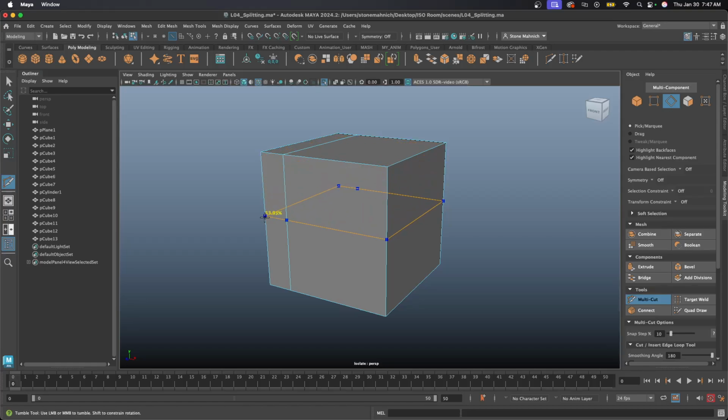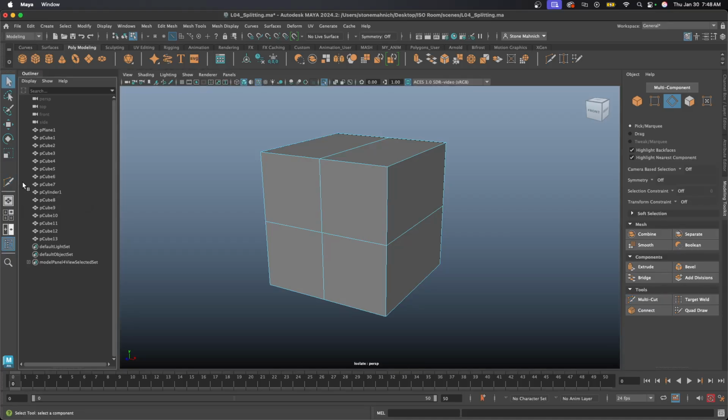So I'm going to place one down, and you place down edge loops with the left mouse click. So holding down Control, left mouse click. Now, if you middle mouse click, watch this, I'm over here, I middle mouse click, and it'll automatically go to the center, which is pretty neat. See that? It'll automatically go to the center. That'll be pretty useful later. To exit whatever tool you're using, I would click on Q. So watch this. It's going to go to my little selection button. I want to click on Q. I like to do that to make sure I'm exited out of the tool.